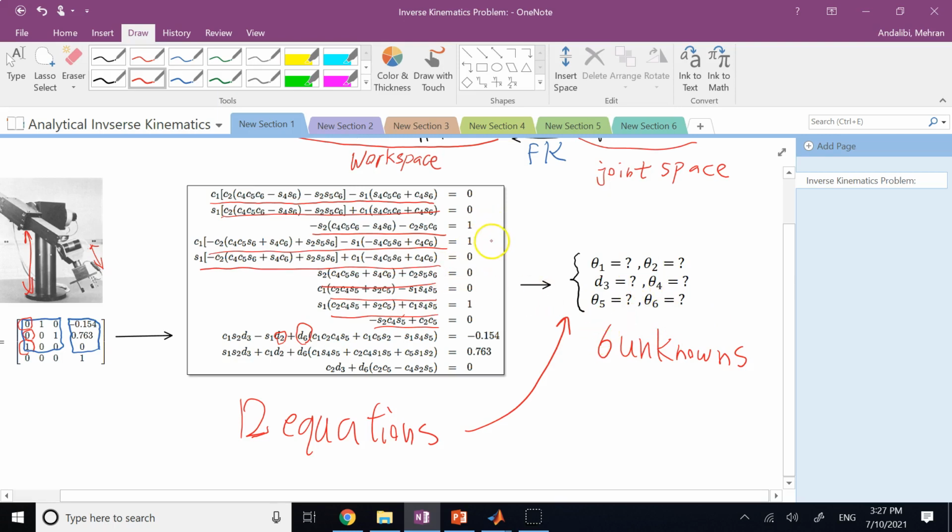You can, because, as I said, although it looks like you have 12 equations, these are not 12 linearly independent equations. The equations do depend on each other. So although you have more equations than unknowns, it doesn't mean that you can never get all of this satisfied. You can, because there are 6 constraints between the elements of the R matrix. But writing those and then using them to get rid of 6 of these equations is a very daunting task.